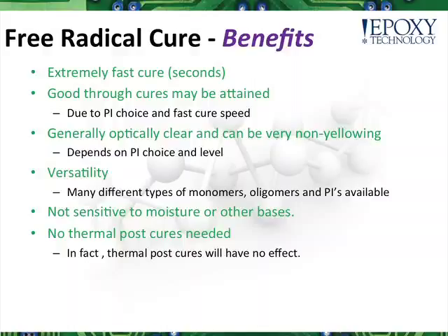From a formulation perspective, for free radical acrylates there are many raw materials out there, many monomers, many hardeners, many photoinitiators, and all of those lead to a lot of variety in terms of what is formulatable. Moreover, they are not sensitive to moisture or basic materials like UV cationic systems. Additionally, no thermal curing is needed, and in fact, thermal post-cures do not affect the free radical systems. Once that light is turned off, the reaction is done.